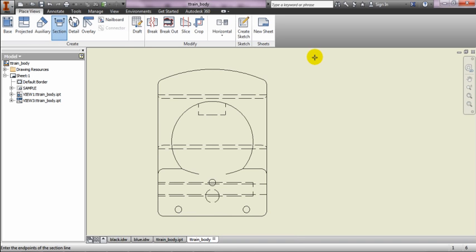So you want to make sure that you hover over all the areas that you want to lock onto. We are going to go straight through the middle, so I'm just going to hover over this area. I'm going to go through these 2 holes here, and I'm going to go through this hole. So now that I've hovered over all those lines, you can see now that I can lock on to their positions. You can see the little dotted line.